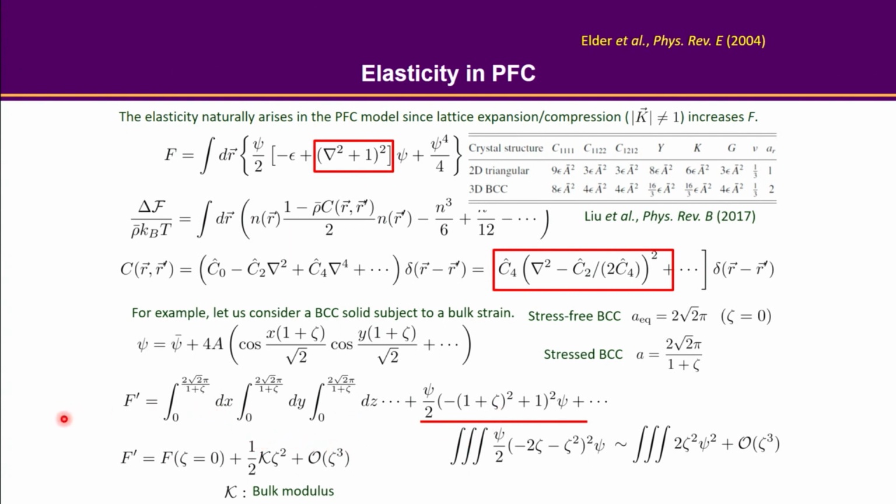And always the increase to the lowest order is proportional to the strain squared, and the coefficient is associated with the elastic constant for the corresponding operation. If you try to apply a shear to your solid, the energy increase has a prefactor associated with the shear modulus.